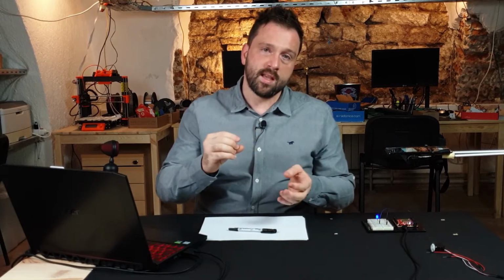And when I said that PWM is used for doing some action, in this case it is dimming the LED. And this is how LED dimmers work in all those light bulbs for LED lighting. In previous lighting technologies, those incandescent lights, you had the option to lower the voltage and get lower brightness. In case of LED, you cannot do that. You can't lower the voltage to get something less bright or more bright. All you have to do is turn on and off more frequently.